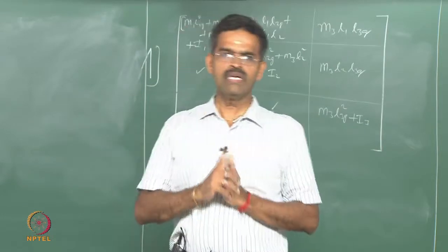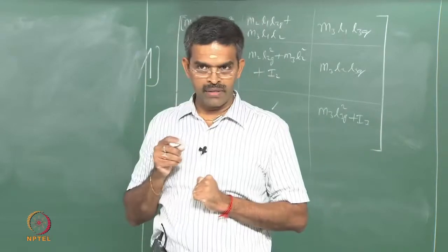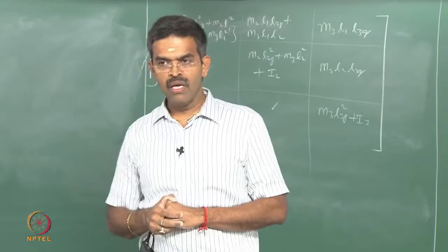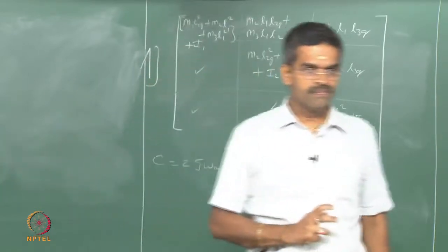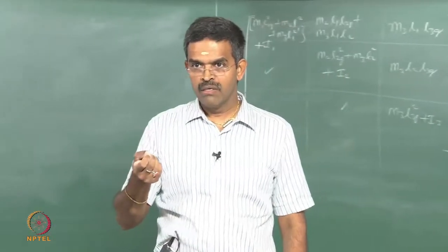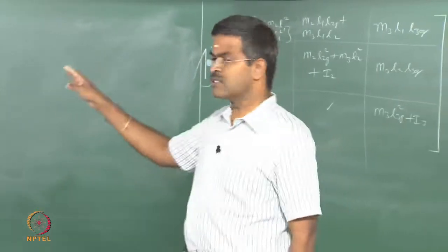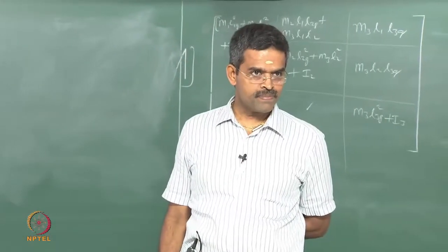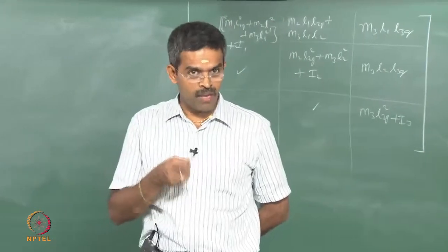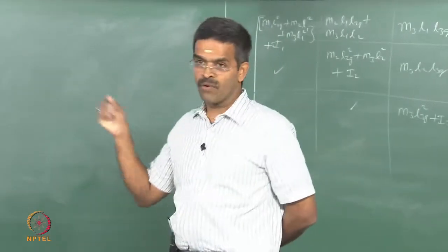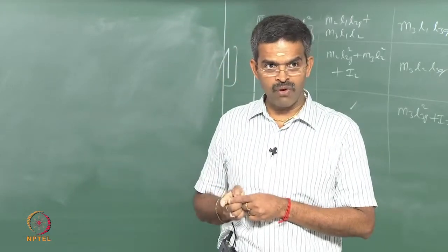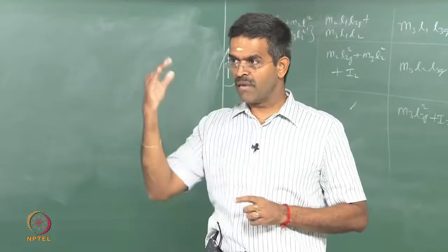So I have a 2 degree of freedom system model here, can easily write the equation of motion and solve. The difficulty is when you have to tune the secondary mass system to the primary system's excitation frequency. This cannot be studied analytically, because in the analytical equations, when omega equals omega bar, you will see it becomes unbounded, because the primary mass system does not have an additional damper. Solution cannot be obtained. So you have to tune this using experimental methodology, by which M2 versus M1 ratio and omega 2 versus omega 1 ratio can be adopted for the given system, so that the response of the primary system can be minimized.